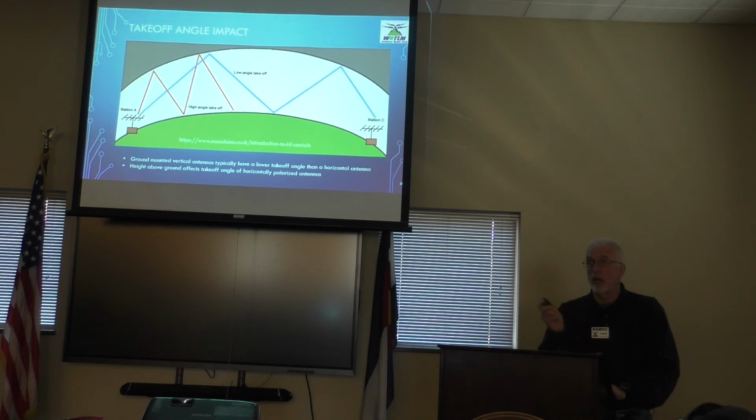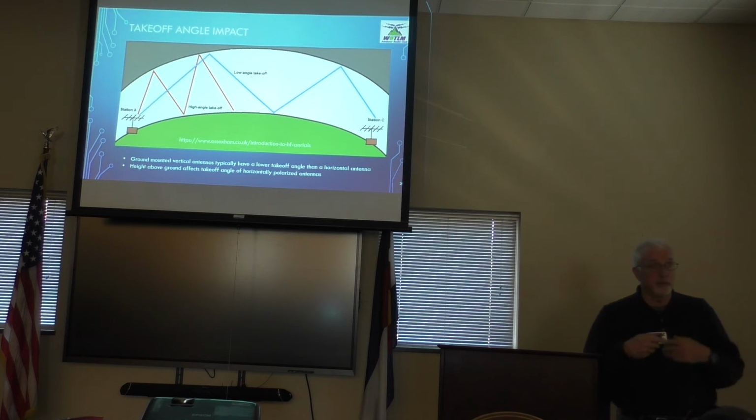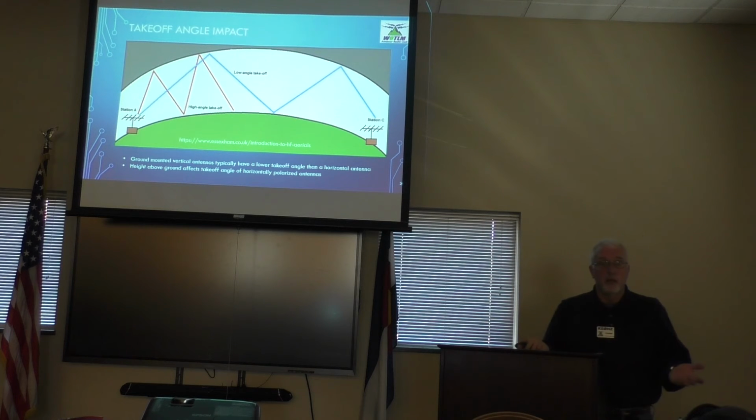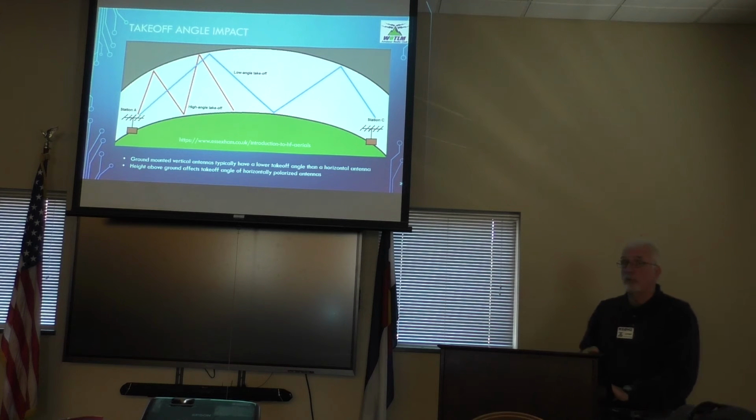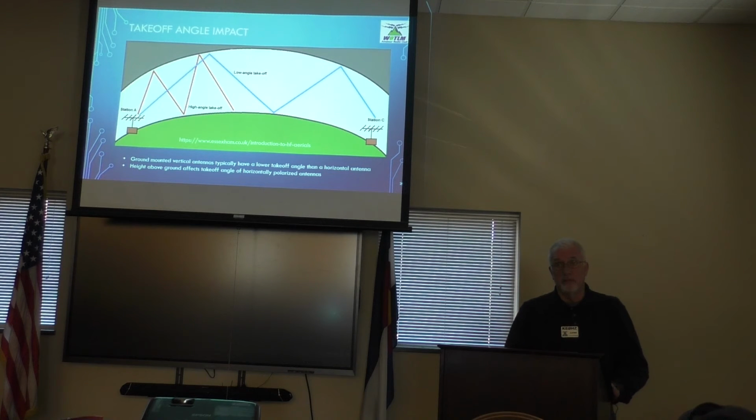I'm not going to cover it now, but this is a decision factor that you may want to make in designing your antenna or your system: who am I trying to communicate with? If I want to work with everybody, you might make some compromises. If you're a DXer and just want to work foreign countries, you're probably wanting a lower takeoff angle and a narrower beam width because I'm going to point that antenna at a particular location.